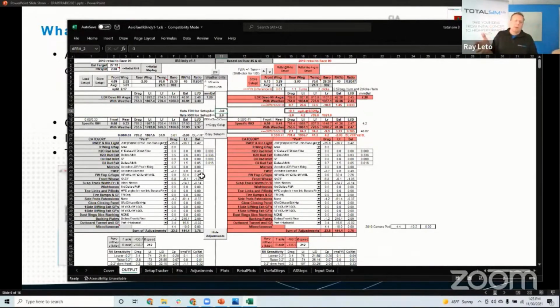And we want to come in between sessions, change the ride height, and we want to know how much front wing we have to change to rebalance the car, keep the balance the same in the middle of the corner, even though we've changed the pitch attitude of the car. We can adjust the wings to make sure that we have exactly the same aerodynamic balance in the middle of the car. Once we've mapped out this whole parameter space, we can create tools like this that allow the race engineer to go in and try different things, experiment, or make a change with confidence.